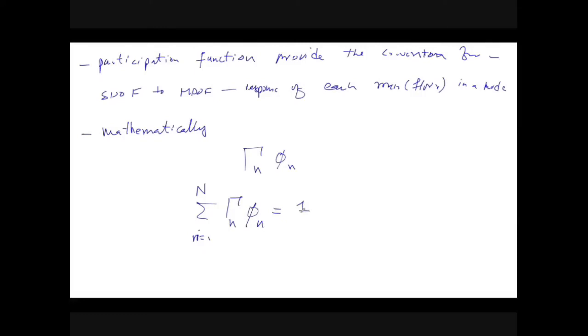In this case, n is the number of modes, which is also the number of levels. So if you sum participation functions for every mode, which are basically vectors, the resulting vector will be just a unit vector. And this describes the accuracy of our analysis, because at this stage you can check if you get 1, 1, 1 for every floor.